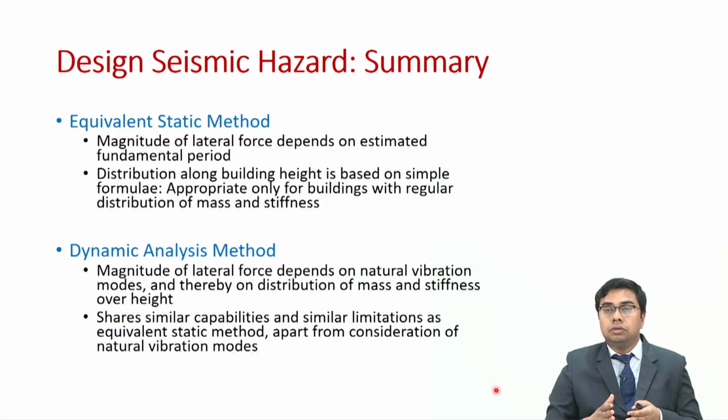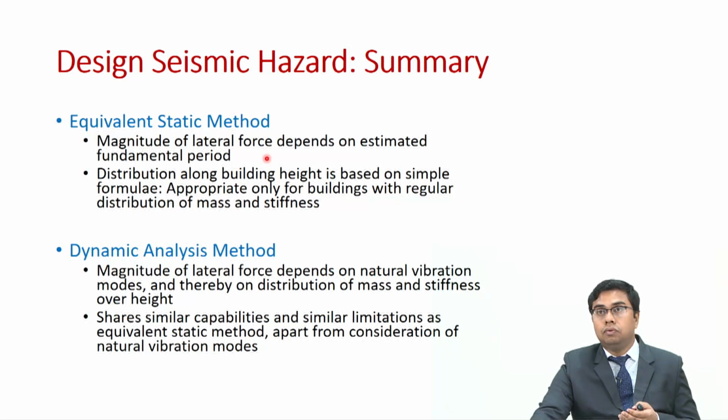As we have looked into the equivalent static method for estimation of design seismic load, we have understood that the magnitude of lateral force depends on the estimated fundamental period and the distribution along building height is based on simple formulae which are appropriate only for buildings with regular distribution of mass and stiffness.